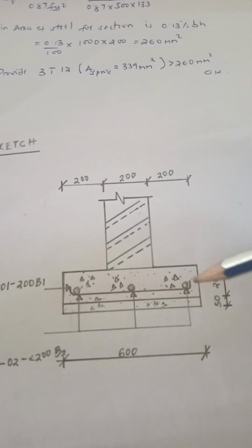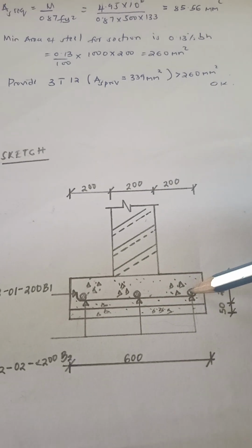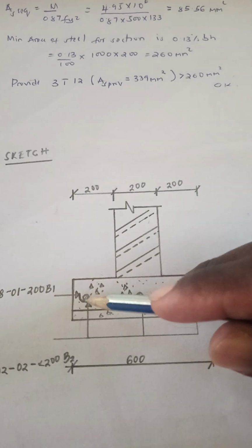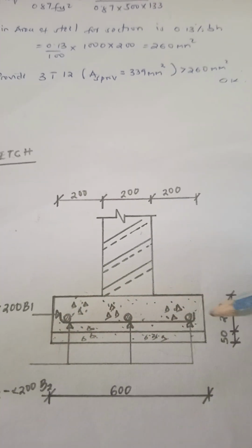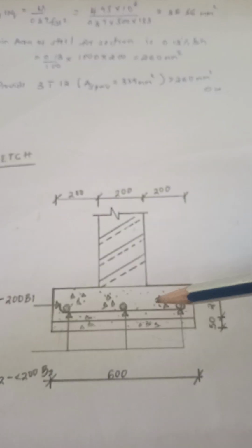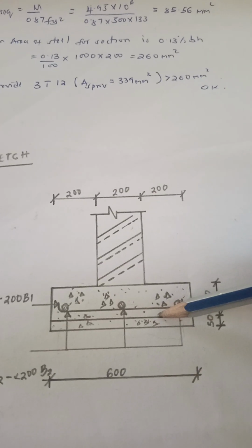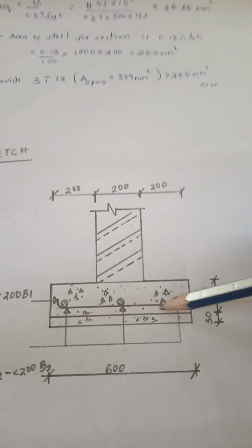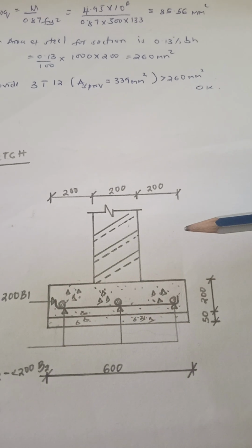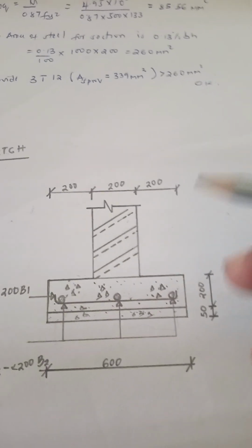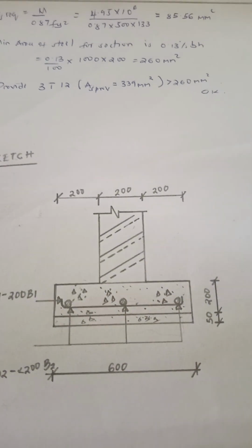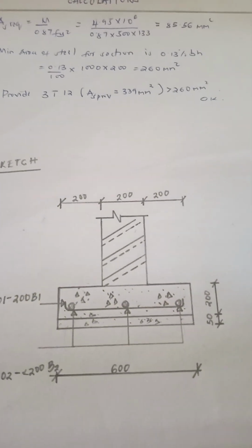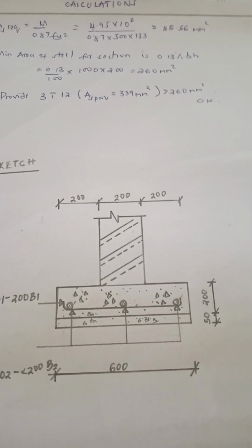Then the longitudinal reinforcement is this one here, the three, which are done to handle uneven soil settlement, and it assumes that the footing is simply supported. Rather, the footing is a simply supported beam spanning over a gap in the soil.